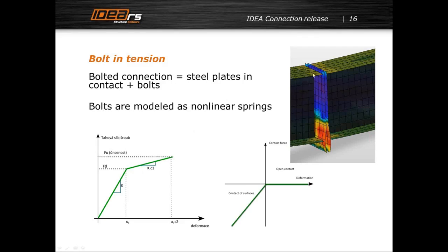We have bolted connections in the model, and in fact, a bolted connection is the contact between two plates. For contact, we have this diagram where in pressure the contact is in action, and in tension the contact is opened, like here.